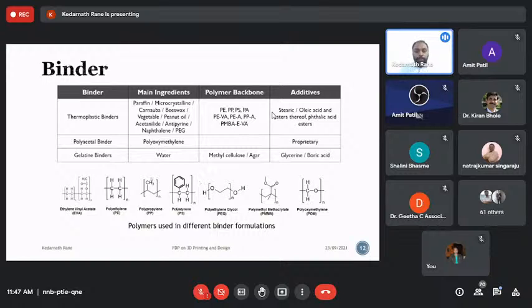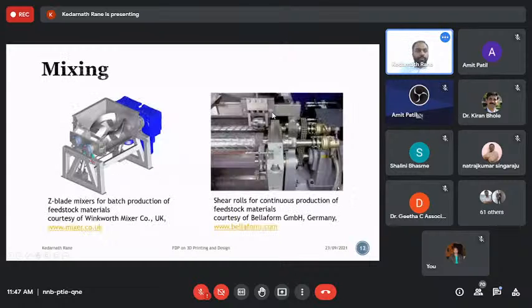So simple polymeric systems like polyethylene, for example PEG or PE or PP, are favorable for this kind of applications. Again, with this kind of system, you need to choose a special debinding system for different kinds of polymers that we can see in coming slides.